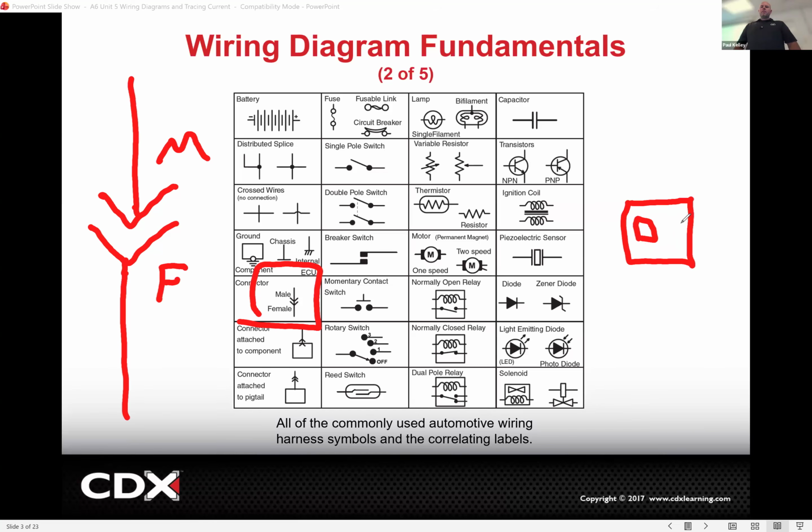When you see the wiring diagram, in every case I can think of, they're talking about the terminals, right? So if you looked at your connector and you had a little male pin like this and a little female pin like this, it's letting you know that side is male. So for whatever reason, if you decided, hey, I want to test this wiring diagram, and you're like, let me check the male side, you'd actually find the connector and see on the wiring diagram, everything flows top to bottom normally.